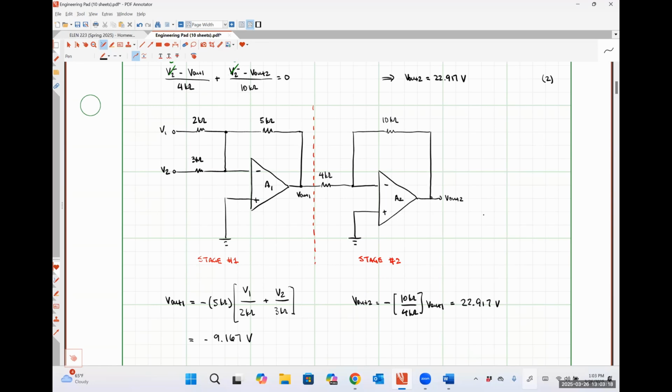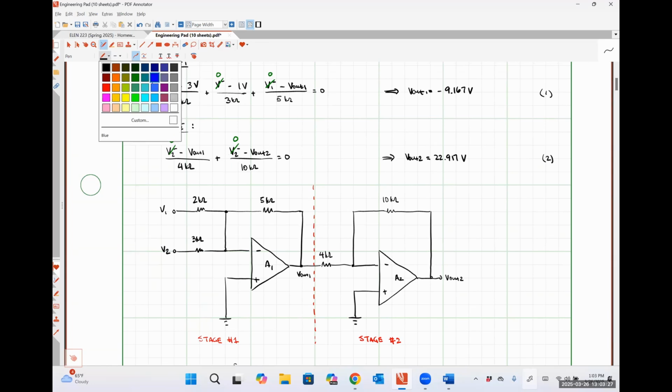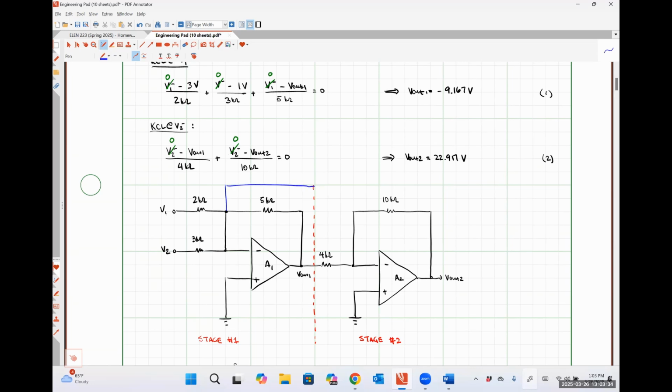and then see if you recognize what's to the left. And the reason why we couldn't do the one in the homework was because it was in an entire loop. So if I were to, for what it's worth, scribble this on top real quickly, if I had a feedback resistance connected, I'm just going to call this RF, from the output of amplifier 2 to the input of amplifier 1, that's nothing that we've ever seen before. And so we can't just use these stages.